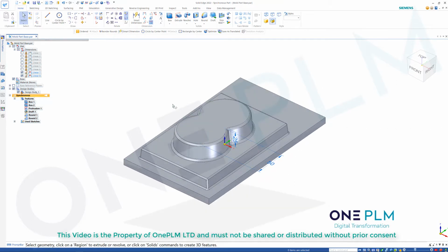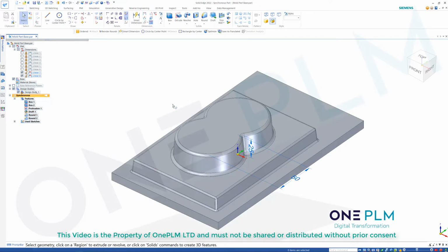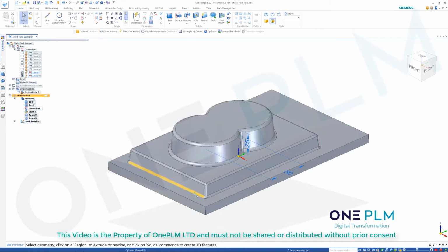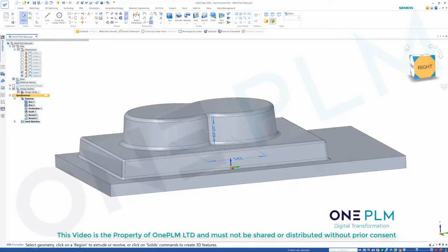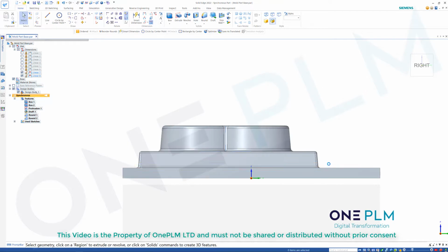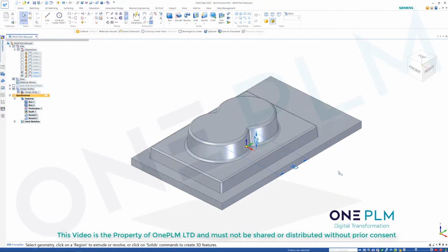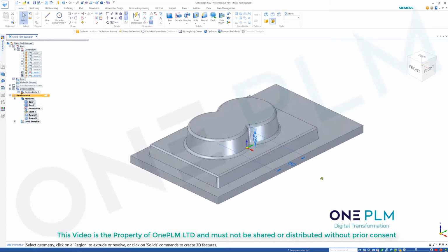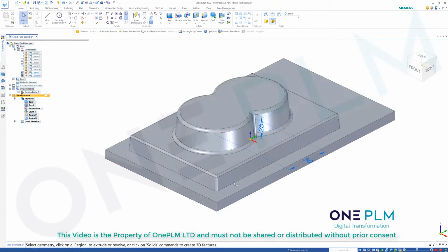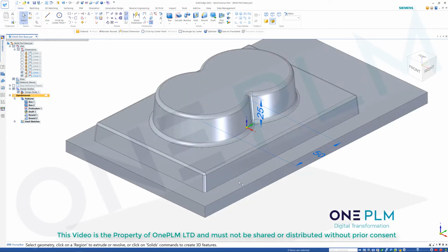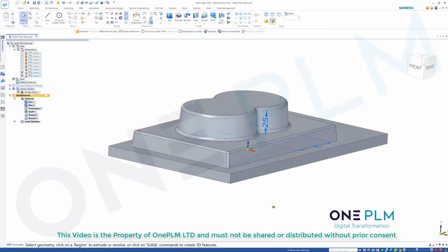Okay, so next, let's have a look at how we're gonna do what we want. Actually, I don't want this round on here. So this is synchronous, so no difficulty for me to go and just fence select and remove that round on there. So next thing, when we have this, we can either have it kind of heated together, or we can have it so it has some kind of clips. So for this, I'm going to do like a clip system.